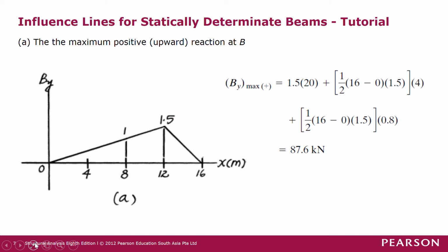So now we look at the first load, the uniform load, which is the dead load. As I mentioned, it is applied across the whole member. So this is the dead load, which is 0.8 kilonewton per meter length. And then the live load will be a moving load. First of all we look at the uniform moving load, which is 4 kilonewton per meter length. That live load, we place it also across the whole beam,